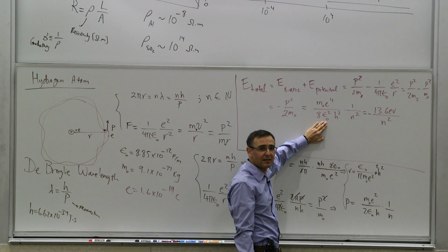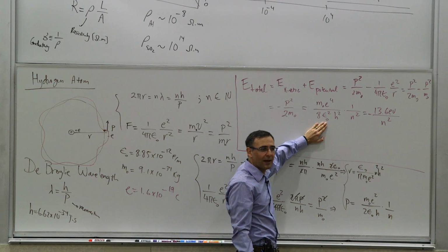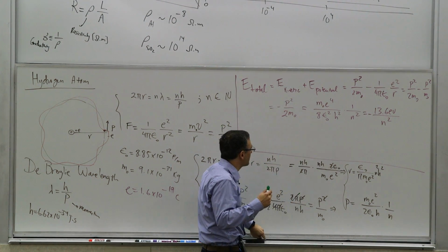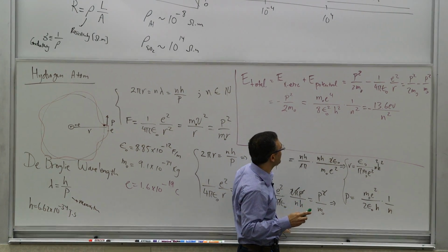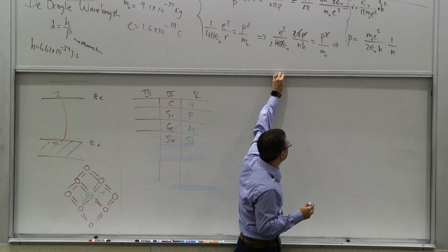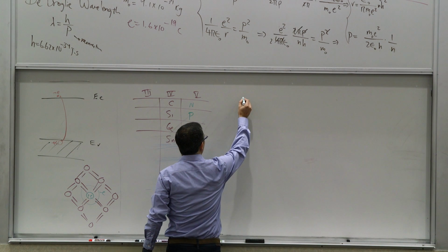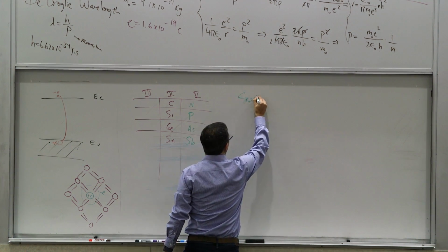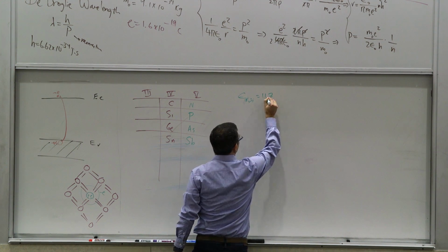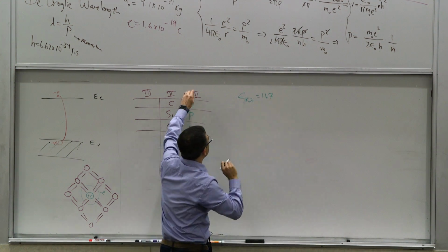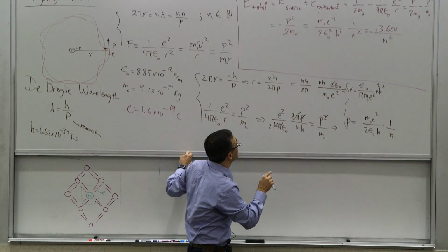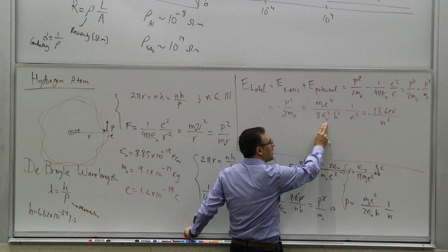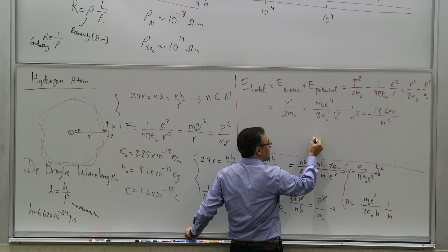Epsilon, right? Yeah. So the permittivity will change. Now we'll talk about why, we can talk a little bit about it. But let's say the permittivity changes. So the relative permittivity of silicon, epsilon relative of silicon, is 11.7. So what happens is that in this calculation that we did before, epsilon is going to get